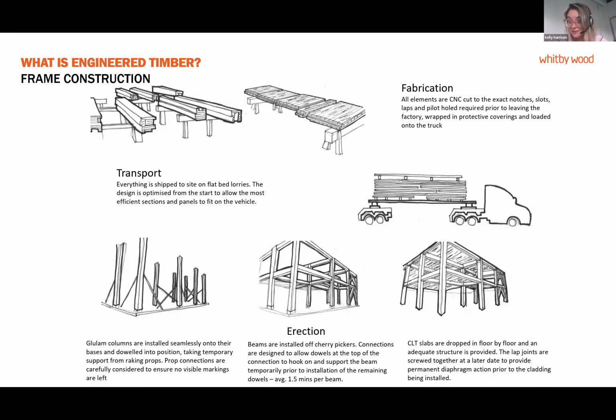just in time normally, and so they will all be very, very well controlled, and the person on site normally has some sort of scanner or iPad, and they know exactly what's coming, and they know exactly where it's going to land, and then which part of the building is going to go up first. So then actually the frame construction, those of you familiar with steel frame construction, it's not that much different. Your columns go up with a bit of propping, your beams go in, your floor goes in.